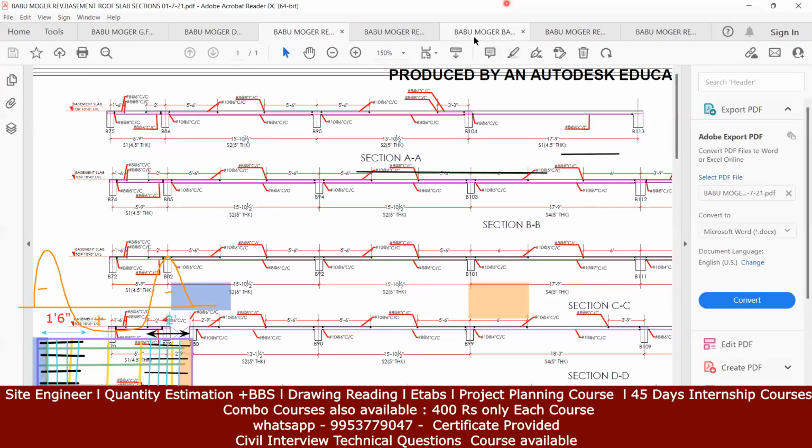So quickly let me draw it. We'll start in this way. So always remember, wherever you have this slab and beam junction, your negative bending moment is going to come. So I have a beam here, I have a slab. Of course, it's a negative. I'll go with a different color. And then we'll go with this. So it's a negative bending moment.